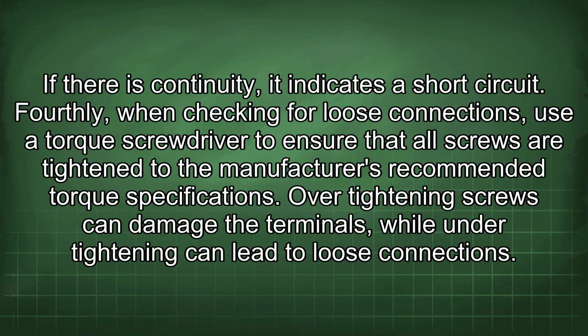Fourthly, when checking for loose connections, use a torque screwdriver to ensure that all screws are tightened to the manufacturer's recommended torque specifications. Over-tightening screws can damage the terminals, while under-tightening can lead to loose connections.